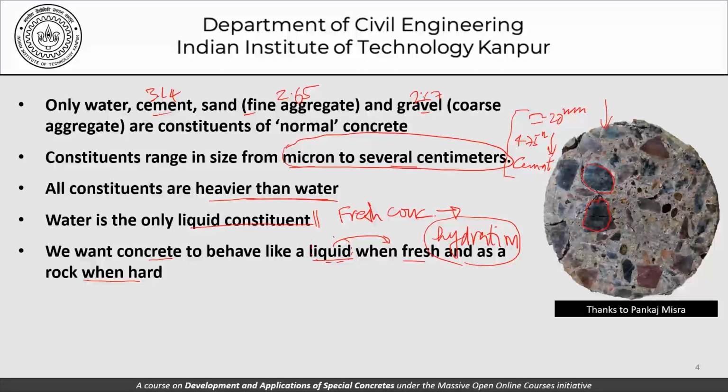But in either case, the cement and the water are the only reactive components. These aggregates, whether they are coarse aggregates or fine aggregates, are only fillers, and they are only there to complete the volume, to provide the volume that is involved. That's one part of it. They, of course, also contribute to strength, so don't hold me to having said that aggregates are not important when we talk about strength of concrete.